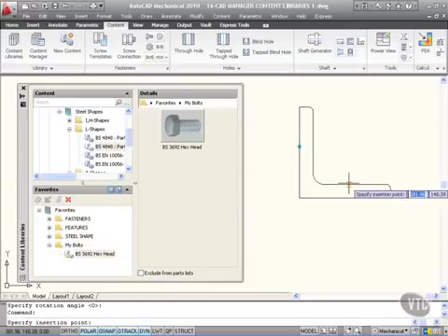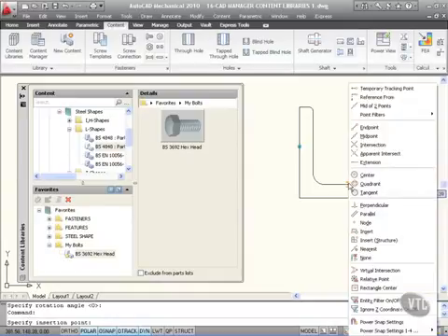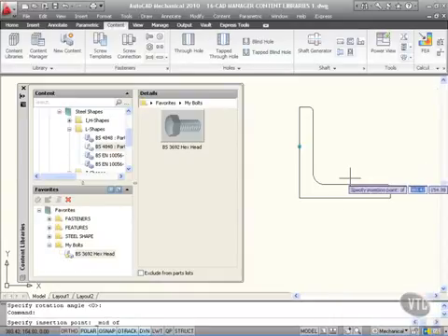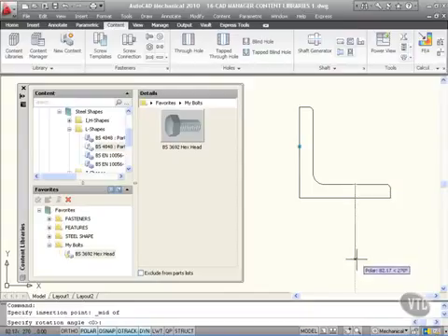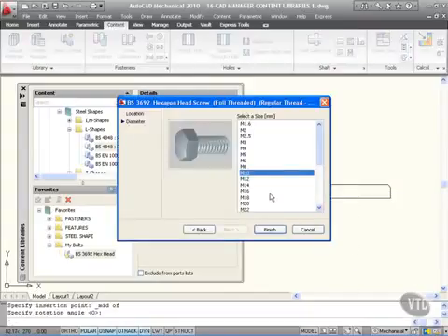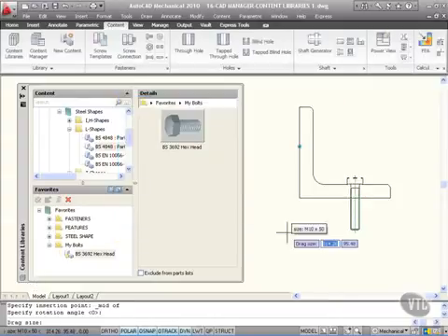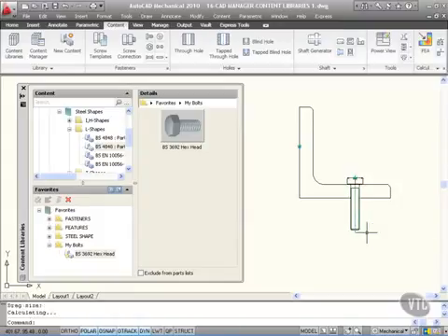And I'm going to specify an insertion point with a shift and a right click and a midpoint snap on the steel section there. There's the midpoint. And the rotation angle, I'm going to come vertically downwards and click. And I'll go for an M10. And I'll finish that there. And that drops that into, as you can see, my section. Now I drag the size there, like so, and just click.